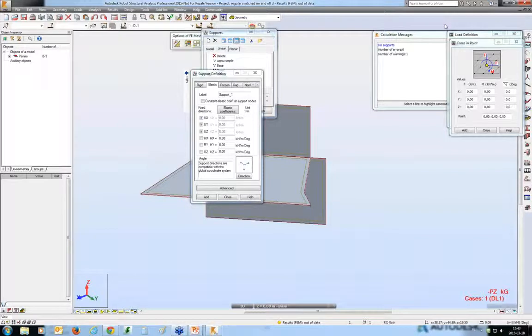So if there is a node in the corner and you move the node, you also move the surface element generated in this location, but you will not change the position of the panel itself. And I think this is the intention of the question. So no, you have to redefine the contour. You cannot move the node.